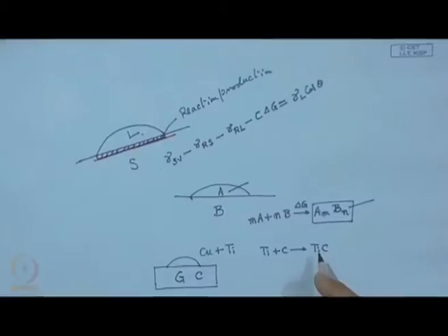So, this is a stoichiometric titanium carbide. So, this stoichiometry will not help. However, if we can have a hypostoichiometric reaction product, that means where we have, say for example, TiC0.5, that means here the atomic ratio is 2:1, in that case this carbide is rich in titanium and it can show some metallic character, and this can be wettable by this copper.